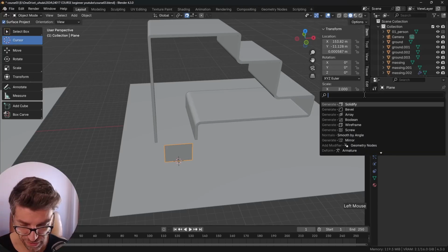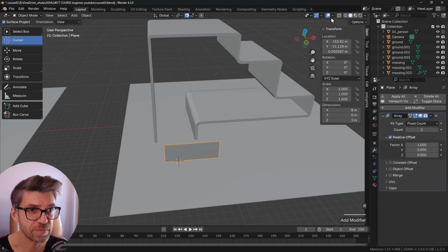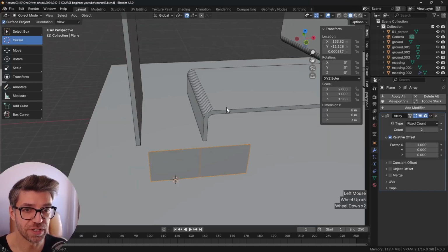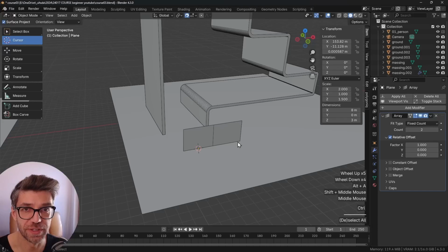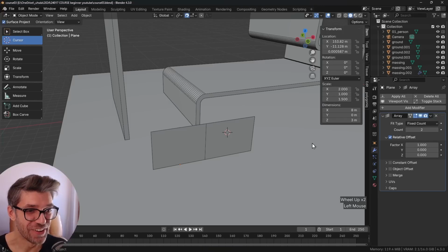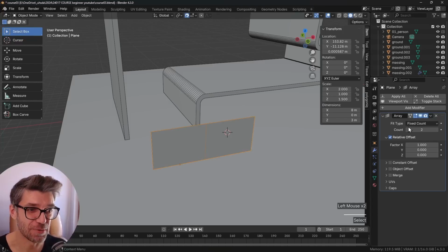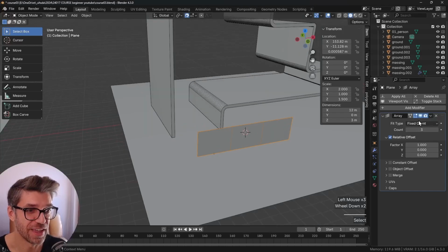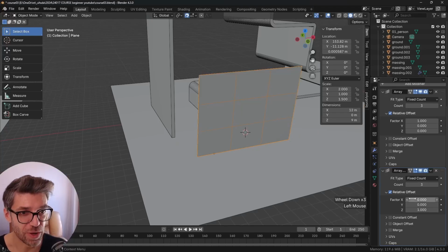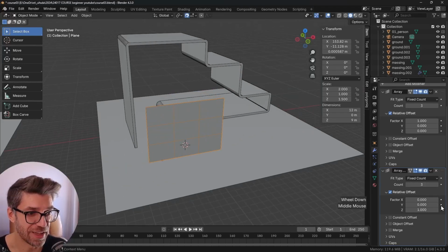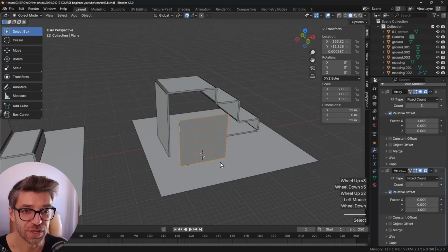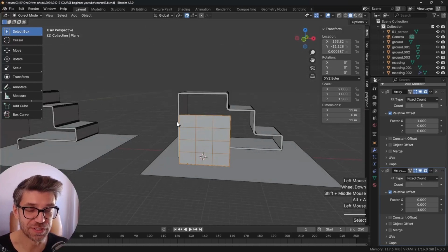Let's go and add an array modifier. And right now, here in the viewport header, I'm going to enable wireframe, so you see the wires a little bit better. Let's also save the file. Always a good idea to do it every once in a while. Double check I'm recording. All things good. Now let's go back to select box and change this count to 3. And now let's duplicate. Factor X is 0. Factor Z is 1. I forget what we had originally, but we can play with this just to see what works best for us. Great. So we have one part of this facade module.